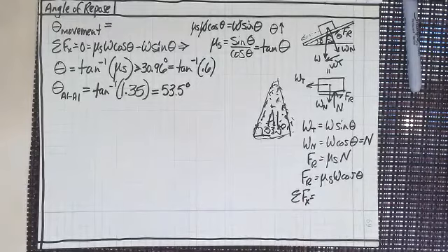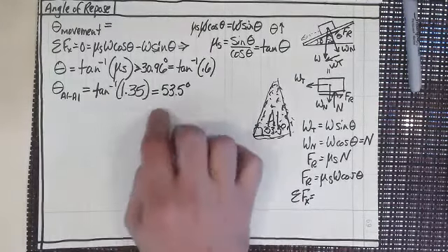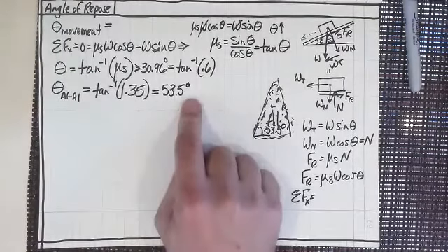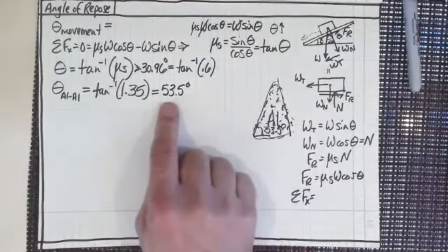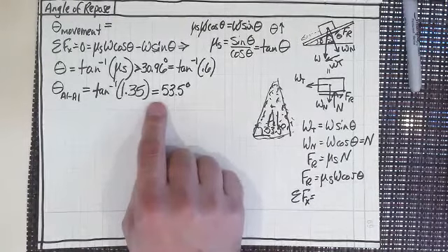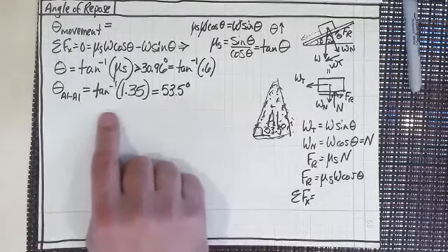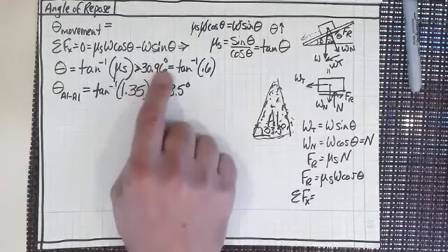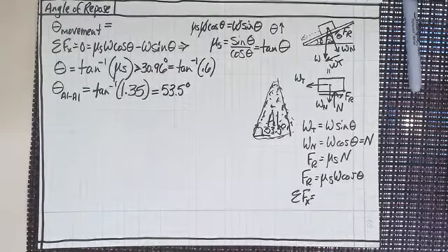Yeah, I'm looking at it, and it looks pretty good. So I just wanted to point that out. We had some other ones here that were sort of high, steel on steel being 0.8. So that's going to be somewhere around 35 degrees, as you can see. But, you know, there's nothing that's infinity.